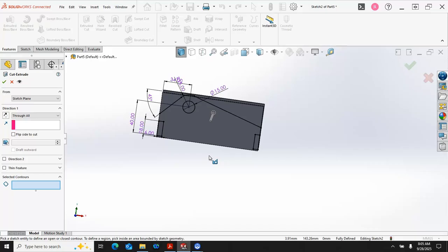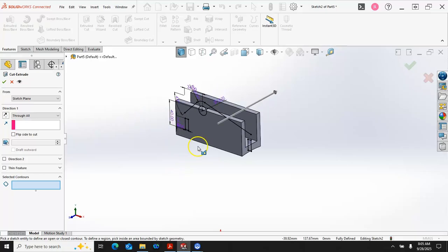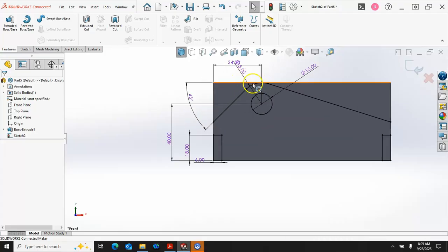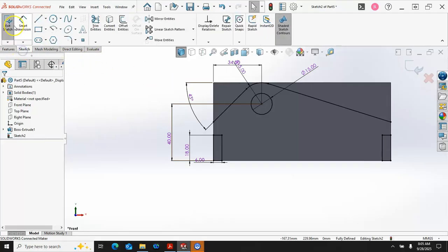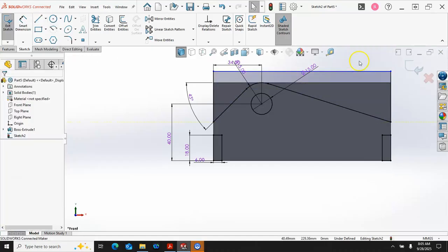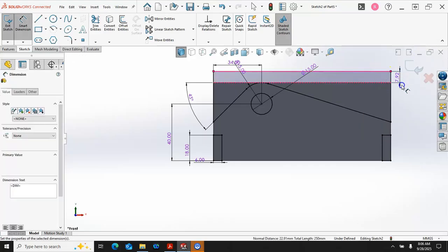So this creates a situation where I have an open and a closed sketch, and very likely it is not going to like the zero thickness where that touches. Even though it doesn't say tangent, we know from our geometry that it was. So if I go to close this off, keep in mind if these were two separate geometries, we could go ahead and just cut it as an open, but I think it's probably safer just to go ahead and close it off.